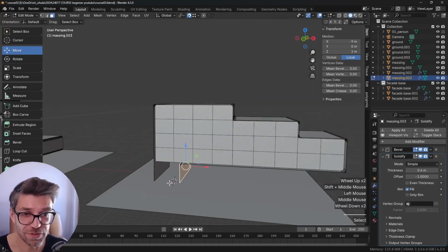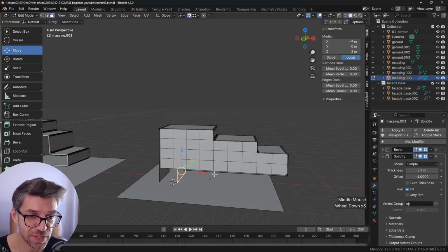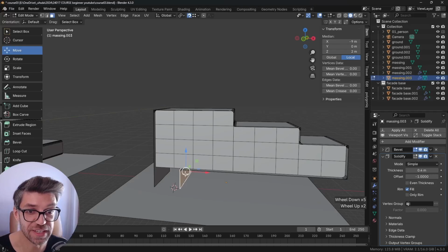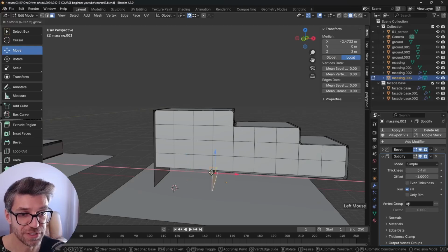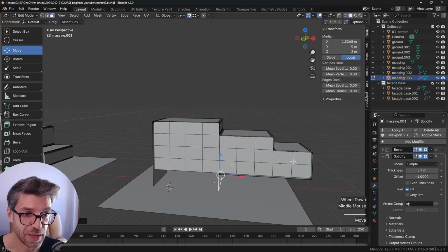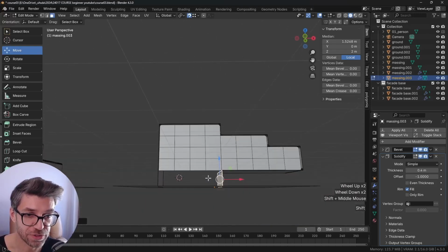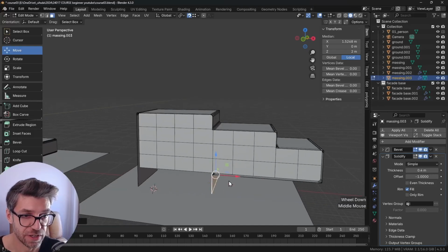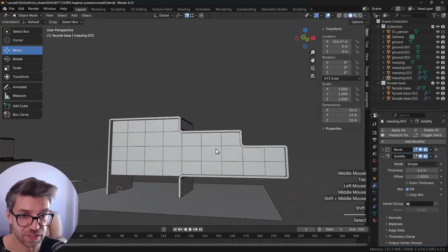And here we're going to have the entrance. Now this building is a lot longer than the one I had before, where I had the entrance snuck in here. Now the entrance is going to have to be somewhere else, just because the corridor is going to be quite long. And when we have such a long corridor, the traveling distances from either side might be too much. So let's stop this somewhere over here. We're going to have the entrance over there, and this is going to be similar to what we have underneath, but slightly different.